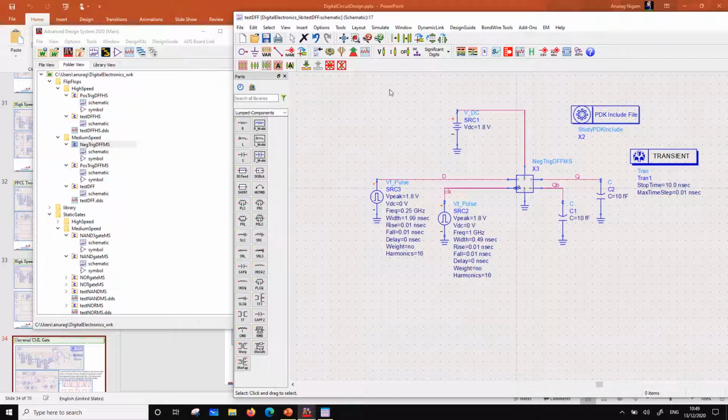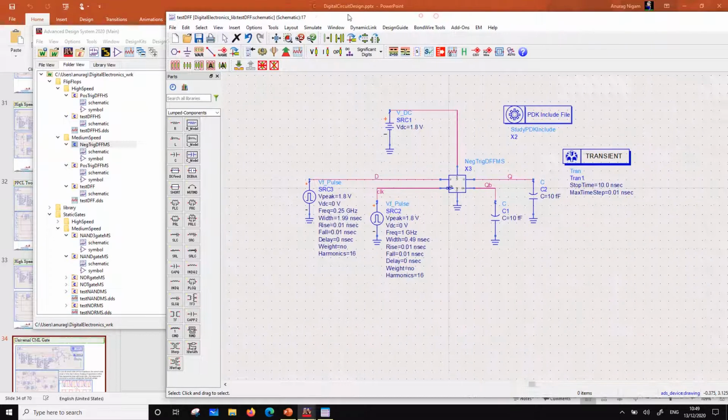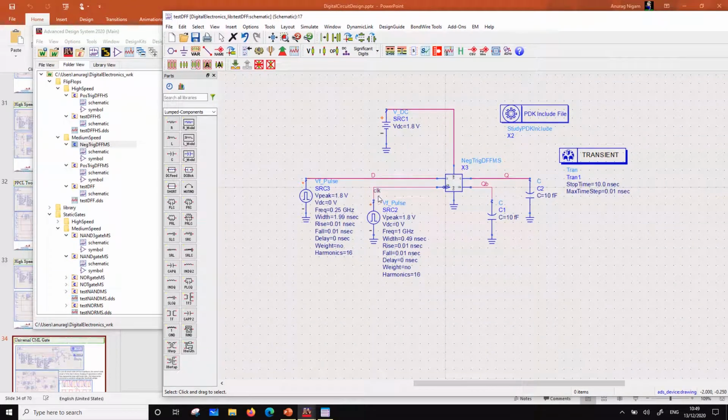Okay, so the two transitions. Actually in digital circuits, one thing you have to be sure of: two actions in a circuit cannot take place on the same clock edge if they are dependent on each other. So you have to be very clear. That's the key. That's why I don't want a D transition at the same point as the clock transition, because then it depends on the delay, and it will have unpredictable results. Once I do the simulation, you might come to know what I'm saying.